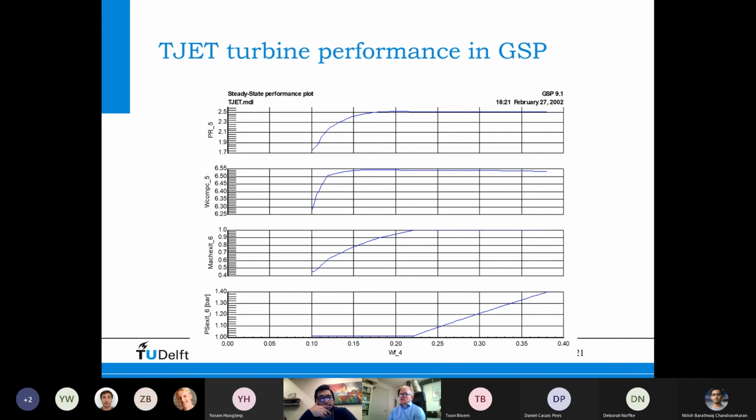And GSP doesn't use that shortcut because there are still small variations, as you can see, because of all sorts of secondary effects. But GSP demonstrates that indeed you can do that. Of course, if you do that calculation and you arrive at some system performance condition, you need to check afterwards whether the point where you actually arrived was indeed choked. So was your nozzle indeed choked? Because you may vary all these parameters as you are converging to your solution.